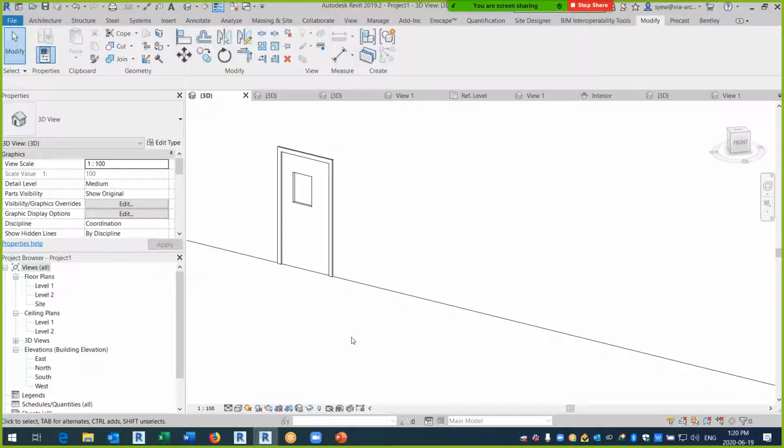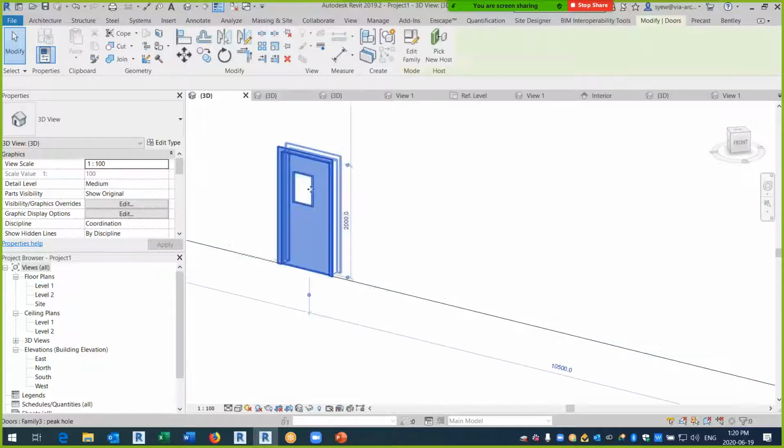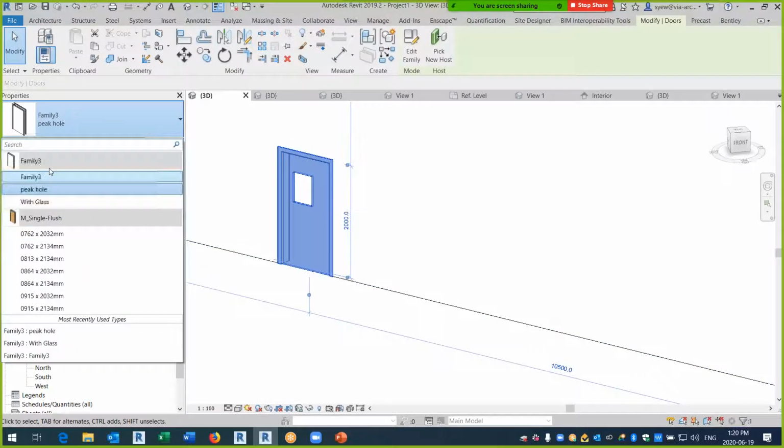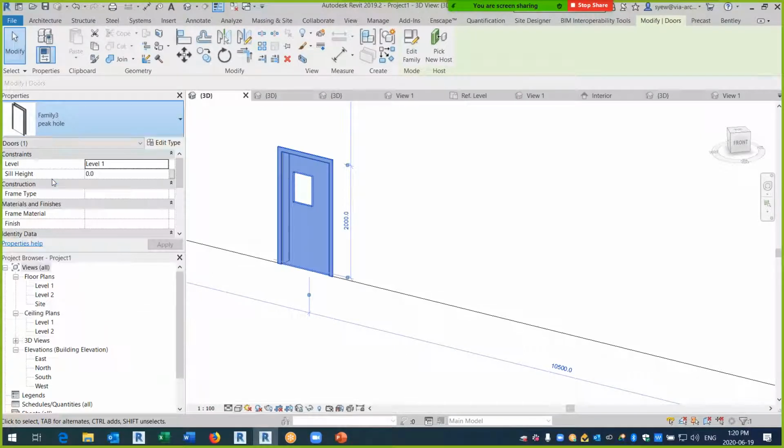I'd like to use this just for starting up if you're doing design. This is a perfectly legitimate way to do it. You have one door that solves basically everything rather than having two different types, as well as a little bit more control. Everything is just one family, and you can have different types rather than having another type for this and another type for that, and running into problems. So those are basically how you swap things out.